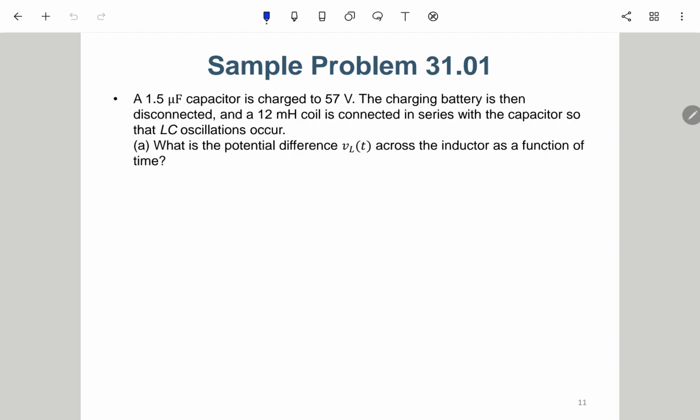Okay, so just as what we have, d2Q/dt2 plus 1 over LC Q equals 0. So this is still the LC oscillation. And then it will still give you Q equals capital Q cosine of omega t. Of course, we will have plus phi, but it just tells you that at the beginning it will be maximized, which means that Q0 will be maximized.